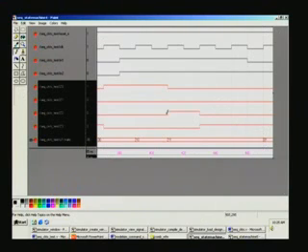I hope you have kept track of all the LEDs for Z0 through Z3. In fact, I forgot to mention, but you can verify one of them here. For the 1 0 state, the same thing you should get here. Z2 must go, so 1 0 is 2, so Z2 must go high.